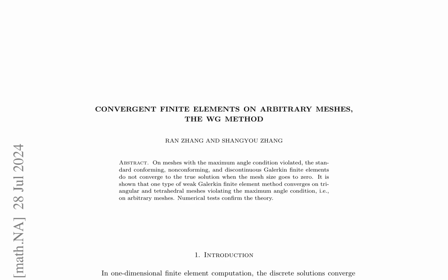The paper discusses the issue of finite element solutions not converging to the true solution on triangular and tetrahedral meshes that violate the maximum angle condition. This problem was first identified by Babuška and Aziz in their work [4], which showed that standard conforming, nonconforming, and discontinuous Galerkin finite elements do not converge as the mesh size approaches zero.